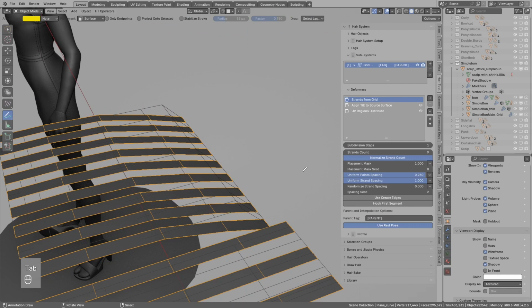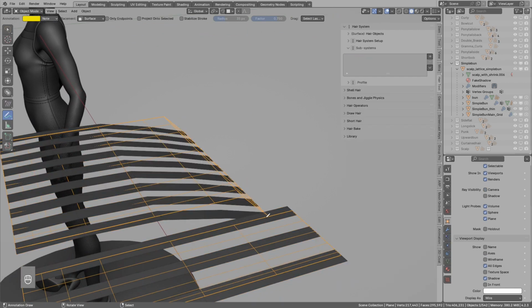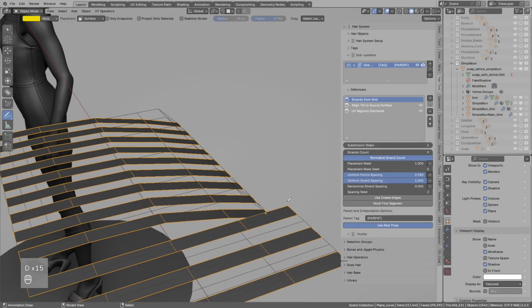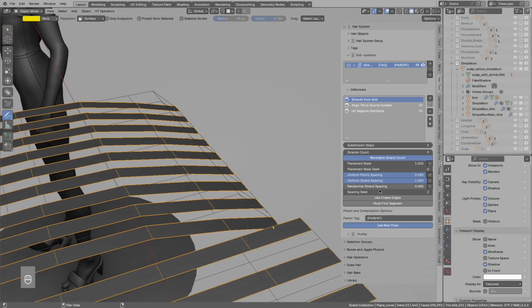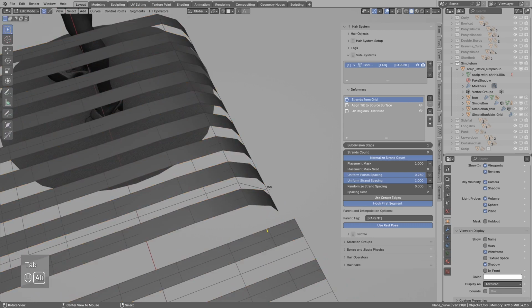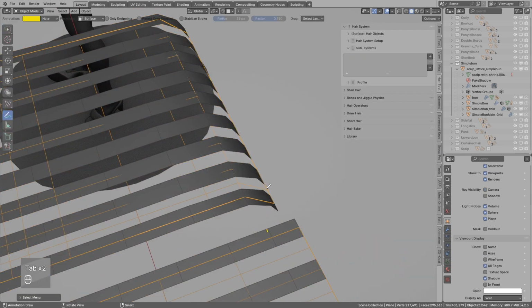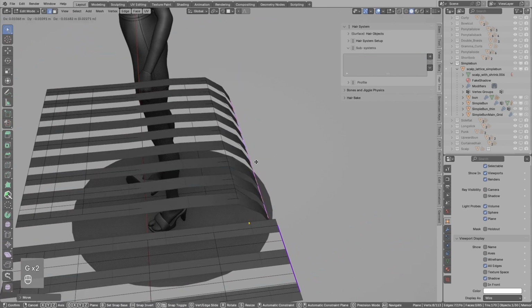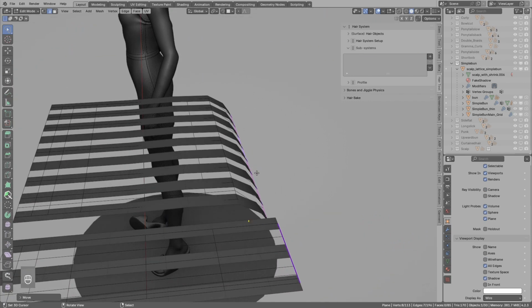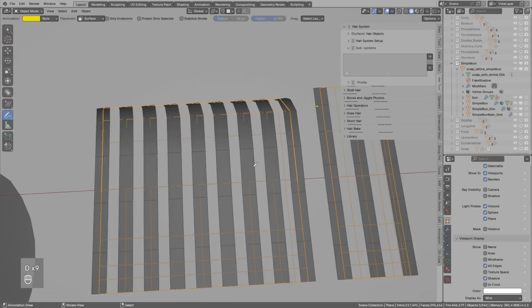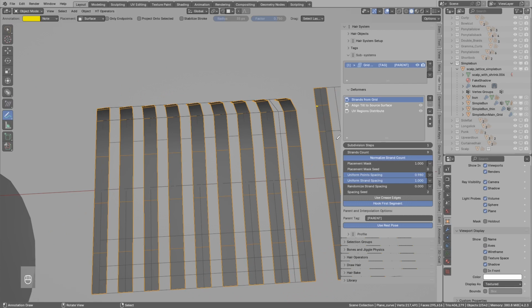And now you see the grid mesh is going to the top like that, but the curve is a bit too smooth. And let's now enable the hook first segment. So with the hook first segment, now the curve will follow more closely the sharp edge segment. This is helpful if you want to embed hair tips into the character head. And that's basically it. Those are all the parameters.